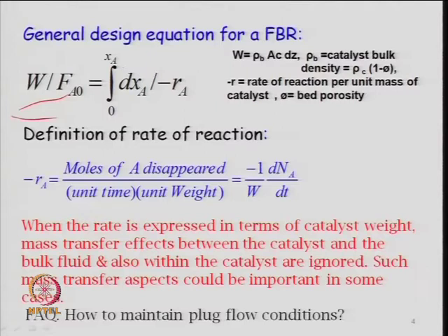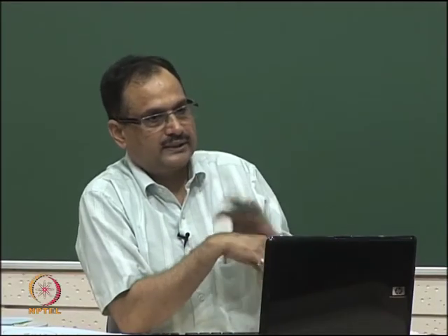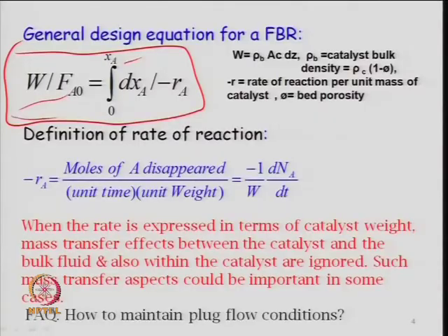The same equation which was earlier in differential form for the reactor has now been defined for sizing a reactor for a given conversion value. Suppose in the lab scale you have achieved some 90% conversion based on the kinetics, and now you want to commercialize this data or commercialize a reactor design. Then you have to use this kind of equation with some hydrodynamic studies. So there is the effect of pressure drop, the effect of particle size, the effect of reactor ID, the internal diameter of the reactor, and the height of the reactor. In total there will be several other parameters also, but from kinetics one can very easily find out the mass of catalyst required for a